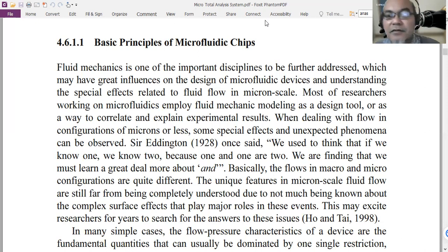Yeah, so if we draw, when the Reynolds number is very small, you have this kind of velocity profile. Okay, this is the middle liquid. The liquid in the middle will have the highest velocity. So this is the factor 2 of liquid velocity. Well, the edge will have the minimum velocity, or maybe even zero, because they are attached to the wall of the pipe or the channel. So this is the characteristic of microfluidics, because the channel is very small: laminar flow.